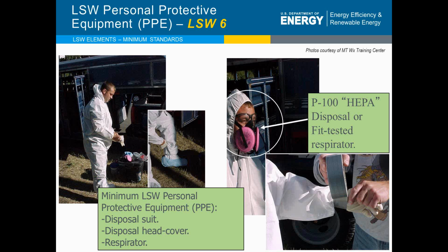We don't want to work in just regular street clothes because of take-home contamination. So our workers could look just like this guy, and the other piece of this would be disposable head cover. This guy with a weatherization agency here, and we would certainly recommend the one-piece disposable suits, good quality suits that have a hood already built into it, with booties.